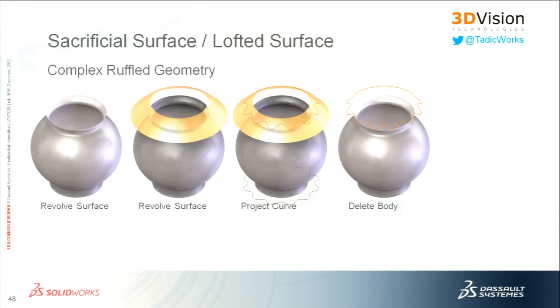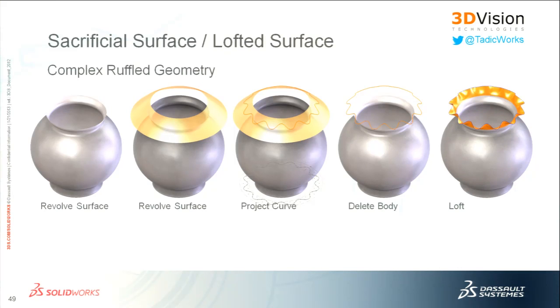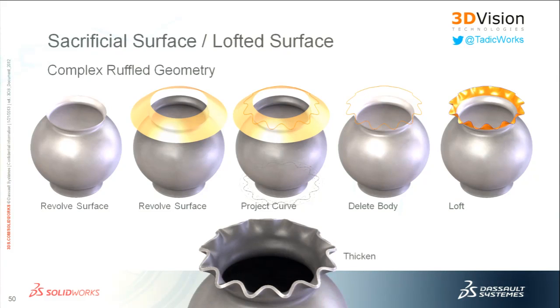So I deleted the sacrificial surface. And then all I had to do was one command, extremely easy, the loft command, loft surface, and lofted between the top circular edge and that projected curve. And that's what I was left with. Then the only thing left to do after that was thicken it, which we've already learned about as well.